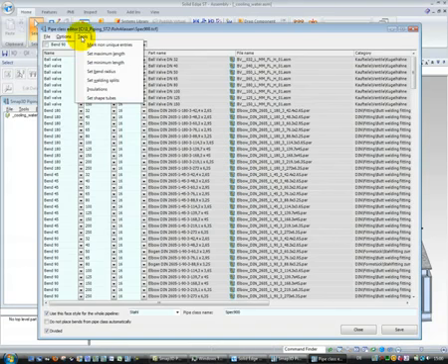Additional to the one-to-one definition, we are able to define additional parameters which control the behavior of the pipe class and the software at the later pipeline creation. Here we have the settings for maximum length definition, minimum length definition, bend radius, welding splits, insulations, and also the settings for the behavior when you work with shaped tubes. That means with non-round profiles to create a kind of pipeline, for example for air ducting or cable trays and so on.